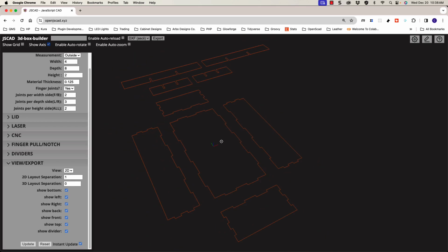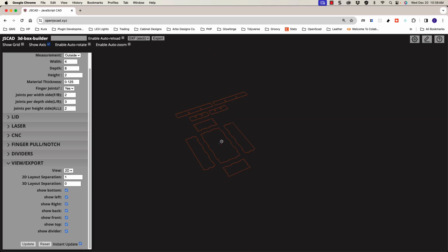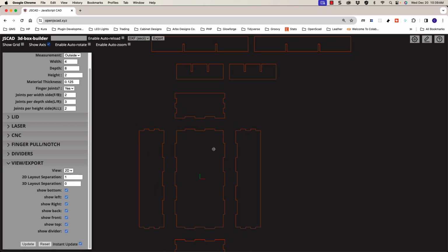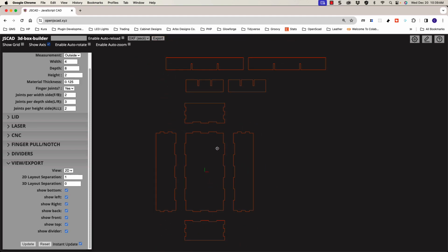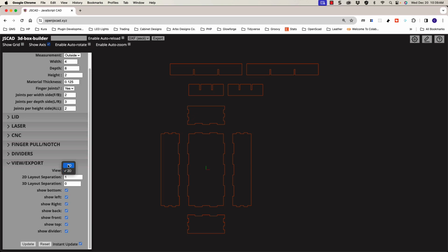So when I'm in 2D mode like this, like I say, you can double click it to get everything to zoom out, and then it will be skewed like this, but once again, hit the T for top view, hit the T key, and then you can zoom in and out or pan, hold the shift key and pan it around. So now you can see the 2D representation of what was going on here.